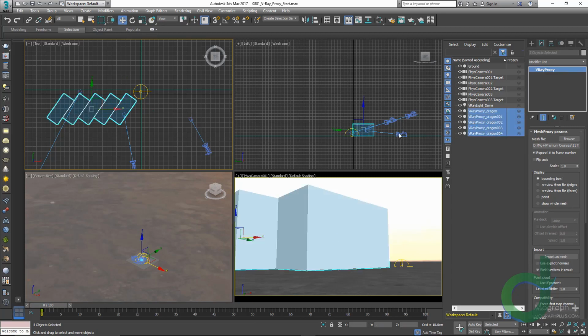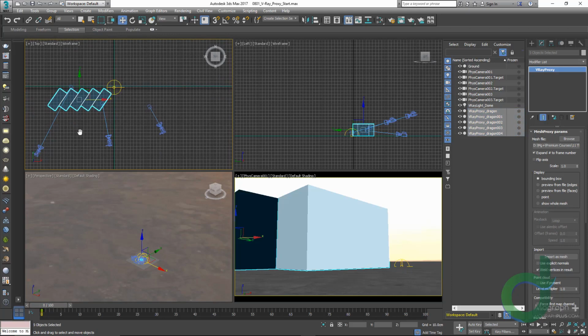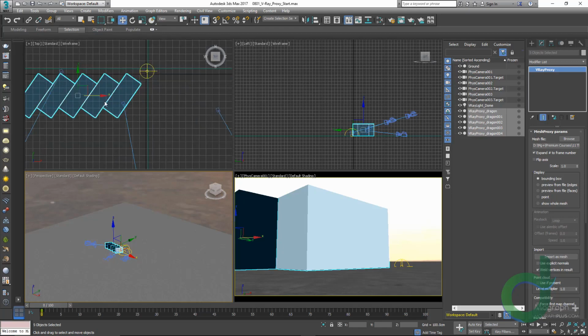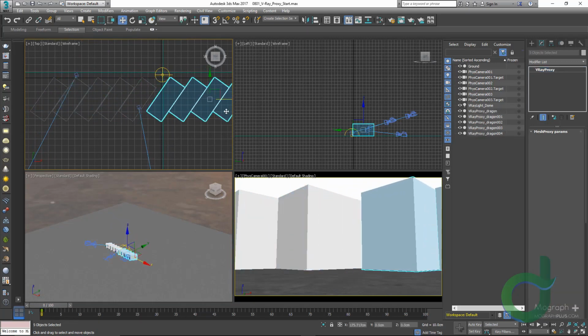It can help with the viewport. It really doesn't matter when you are having 100, 200 copies, but if you are planning to have thousands and thousands of copies, it would be better to set the display to bounding box. Now select all the existing ones and shift drag them on X to the right side.